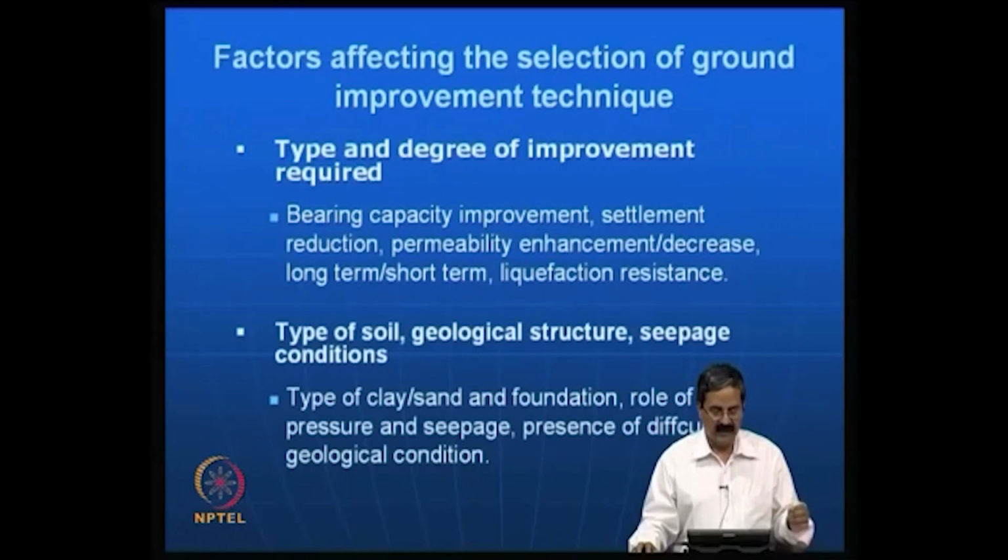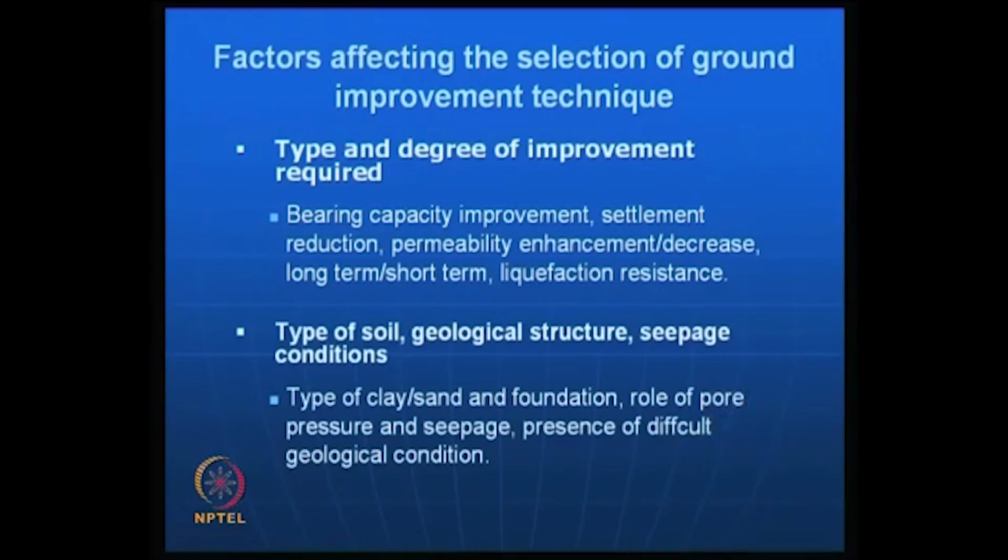So, what is long term, what is short term? This is another important point, because a soil is getting consolidated, right? We know that. Say, for example, I have seen in many places where you need improvement only for 1 year. So, that is short term. Say, for example, you start loading on a soft soil. You are constructing a highway embankment 3 meters or 4 meters height on a soft soil area with sand and all that you are dumping.